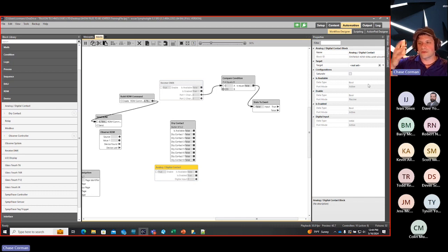So that will show the analog, sort of digital contact, is looking for a varied voltage. And so it's actually going to give you a number. It's going to show you in millivolts how many volts it's reading. That is set up to receive anywhere from 0.1 or 0.0001 volts up to about 11.5. The input node is not rated for 24 volt dry contact. So if you need that from us, we provide an XT2.